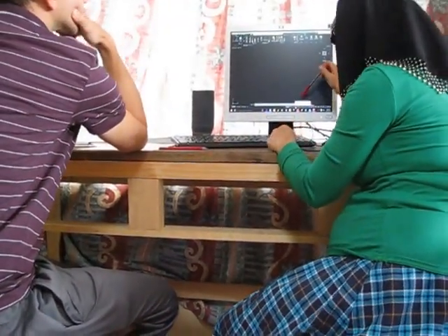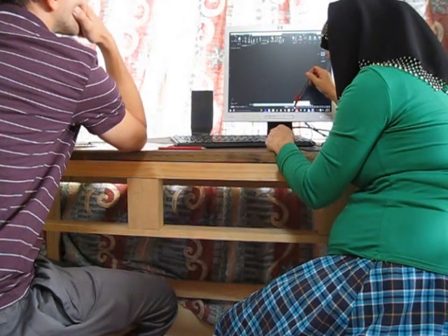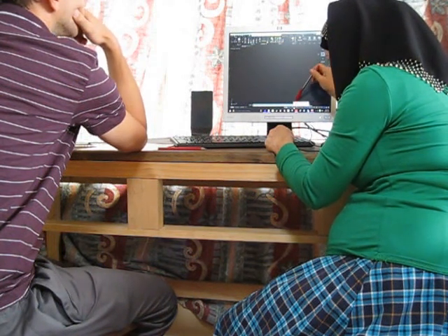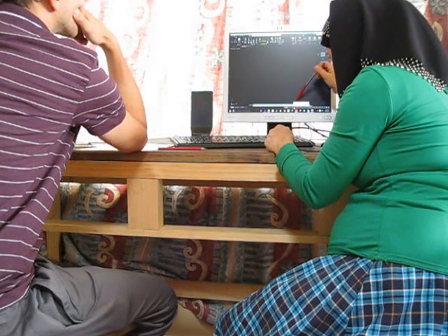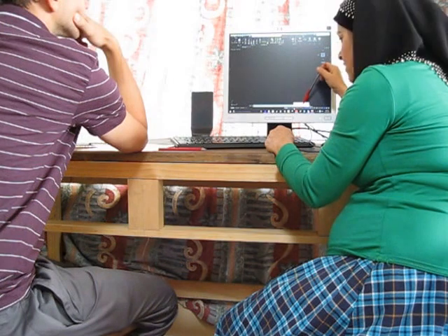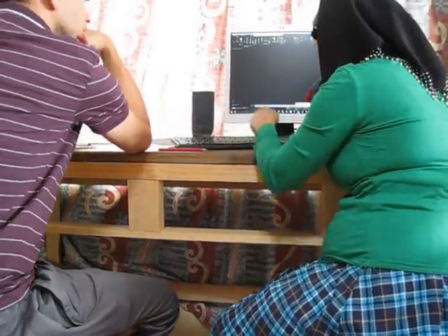The first item is two lines vertical to each other, showing a 90-degree angle. It's called restrict cursor orthogonally. It's off, and we have to turn it on. Underneath is written ortho mode or F8. So either you press F8 on the keyboard.